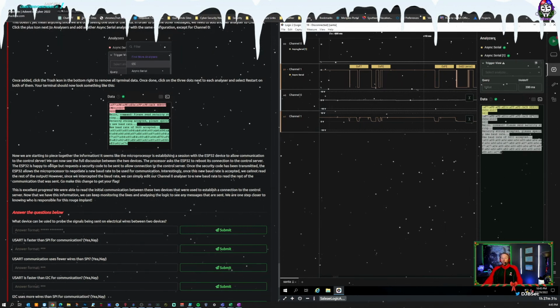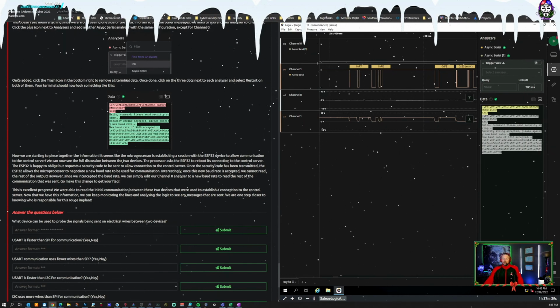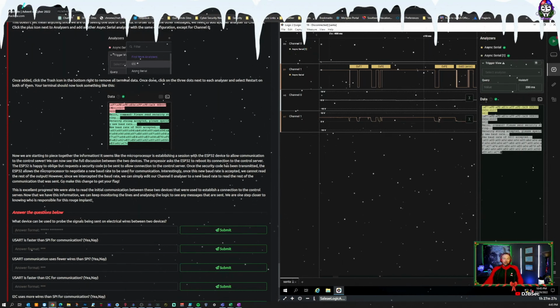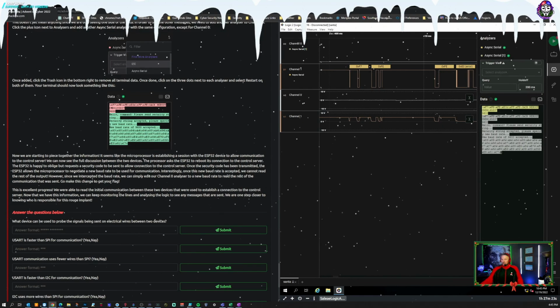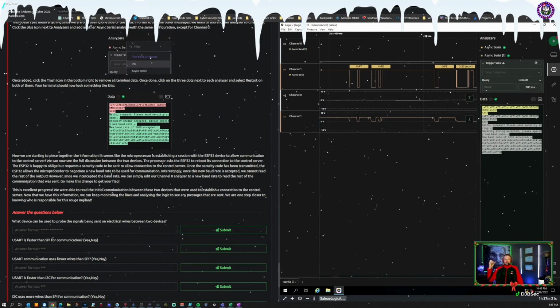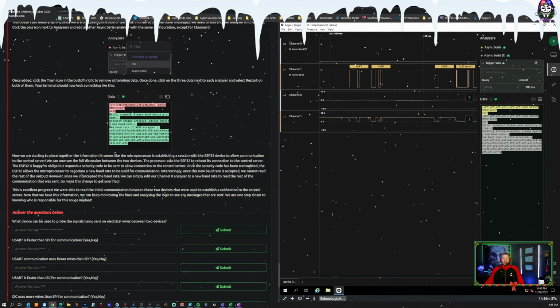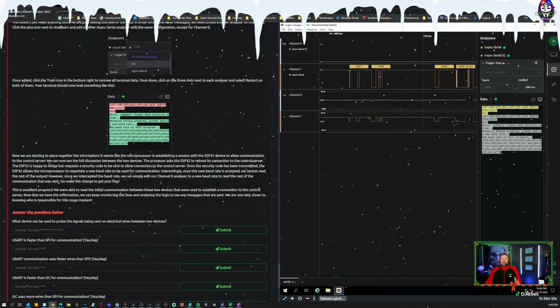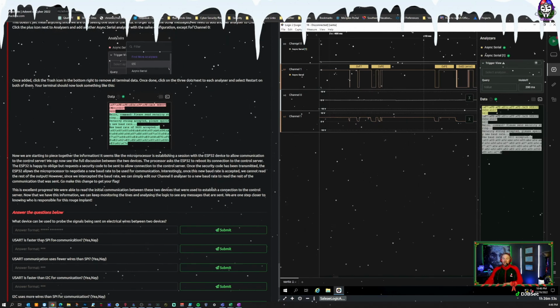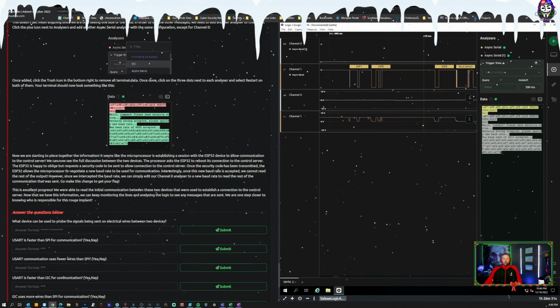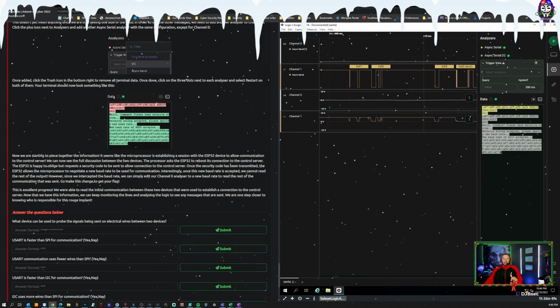Interestingly, once the new baud rate is accepted, we cannot read the rest of the output. Emotional damage. However, since we intercepted the baud rate, we can simply edit the channel 0 analyzer to a new baud rate and read the rest of the communication that was sent.